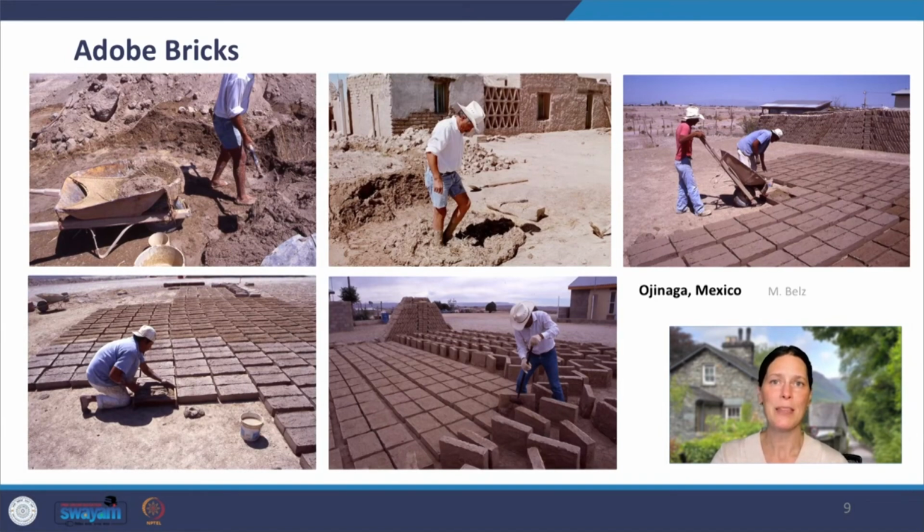Earth building can come in many forms, as we've seen, and an earthen wall can be constructed with hand-molded clay balls of earth, cast bricks, or slow layering of earthen levels that are tamped down and rammed, to name only a few methods. Adobe often refers to a brick. Earthen construction is more general and will encompass cob and those other methods, as well as plaster. The material is primarily clay, with enough sand to stop cracking, and straw and other fibrous material to add tensile strength and bulk.